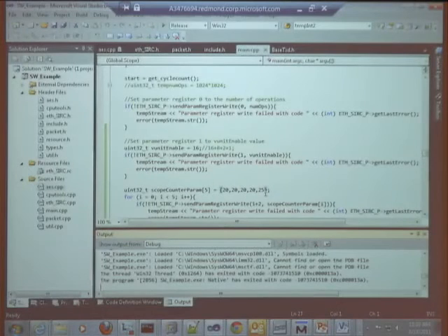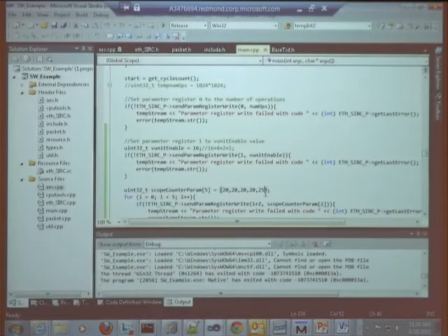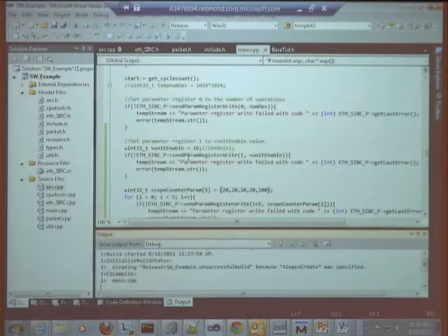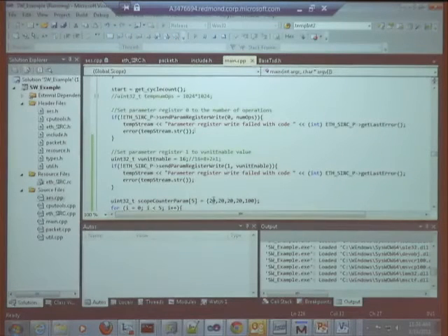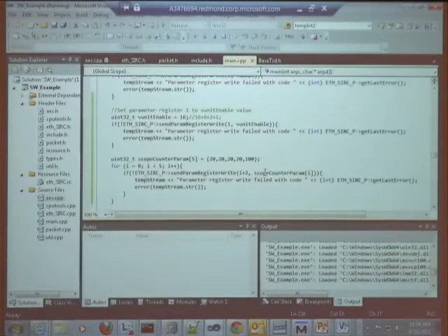I added 5 more clock cycles. It was 23. Now it's 28. So let me do 100. I'm going to wait 100 clock cycles. Okay, it didn't fail this time. So it's like I'm changing the time scope and then checking if that assertion failed or not. So I can do the same thing with other assertions here.